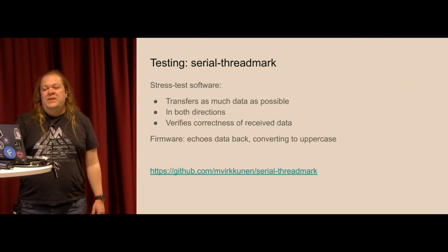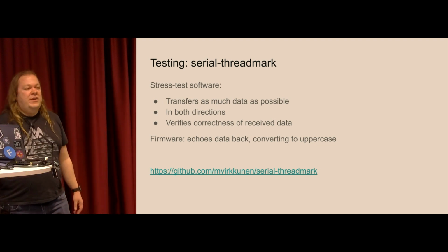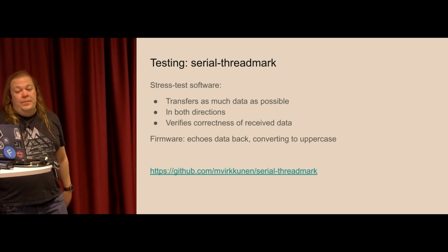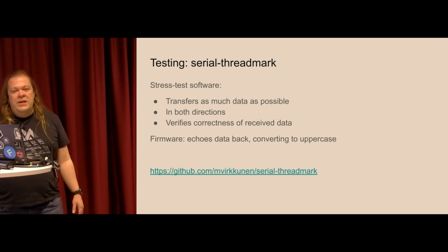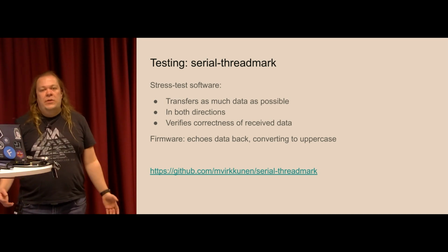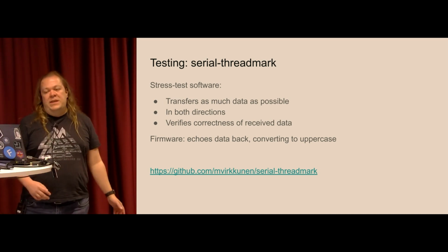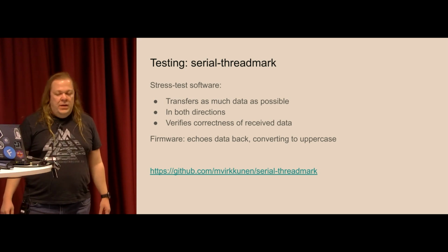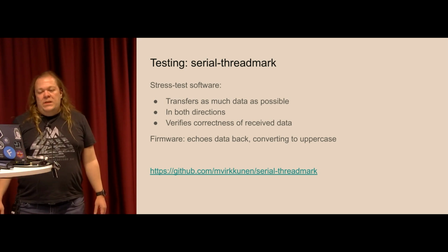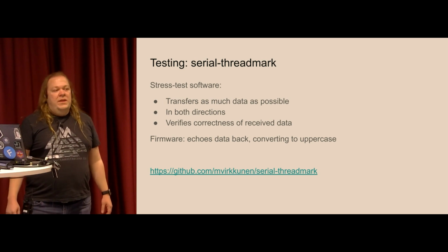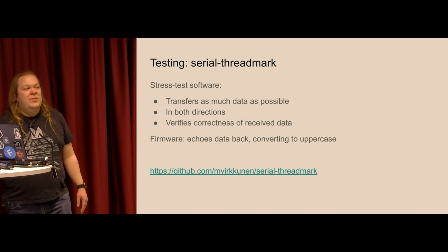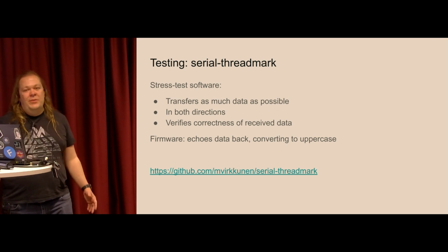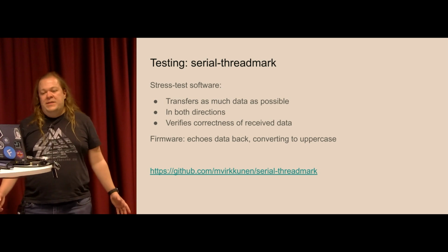And then there is quite an interesting test, just a serial benchmark, but it is a stress test in a way, because it tries to send as much data as possible toward the device, and the device acts like a regular serial port, but it echoes all the data back in uppercase. These tests may not be trivial for the initial implementation, because sometimes multiple requests may arrive one after another, and sometimes due to some bugs you will not be able to handle one of them, and then the whole packet is lost.